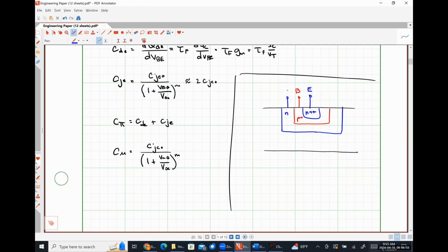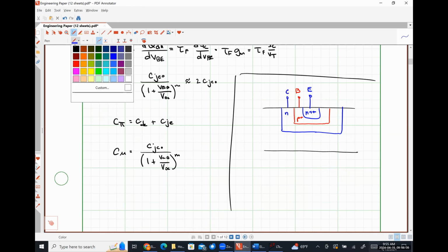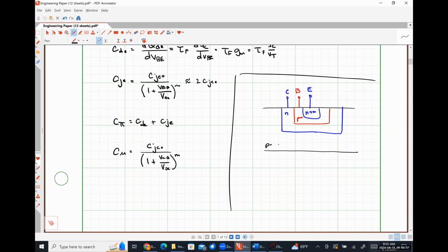Draw that as a capital C. And down here, we might have a P substrate, particularly if we are designing a, I don't remember the exact word, but effectively there is a complementary BJT technology, just like there's a complementary MOS technology that allows us to fabricate N-channel devices and P-channel devices on the same substrate. We can do literally the exact same thing with a BJT.